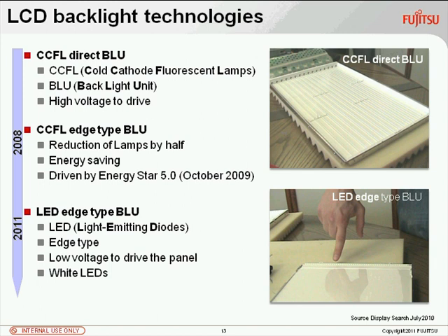These are lamp tubes like those used in the office to make the light. You see these lamps here. We opened the 26-inch monitor and took away the LCD module, so you see into the backlight. And these stripes here, these are the CCFLs.